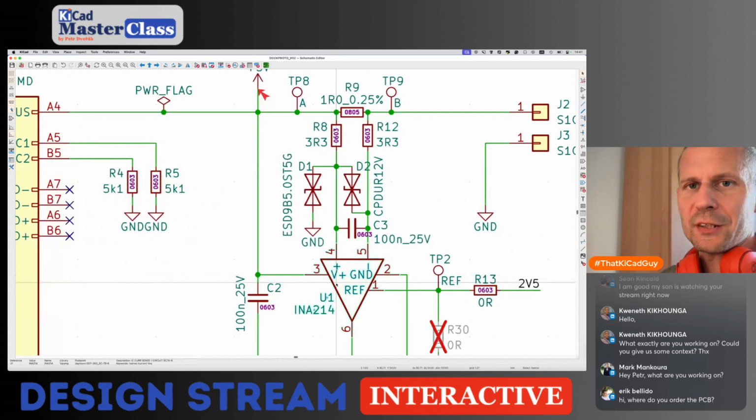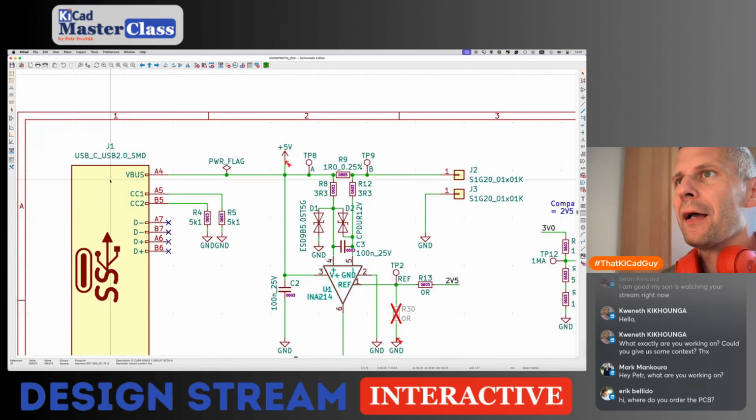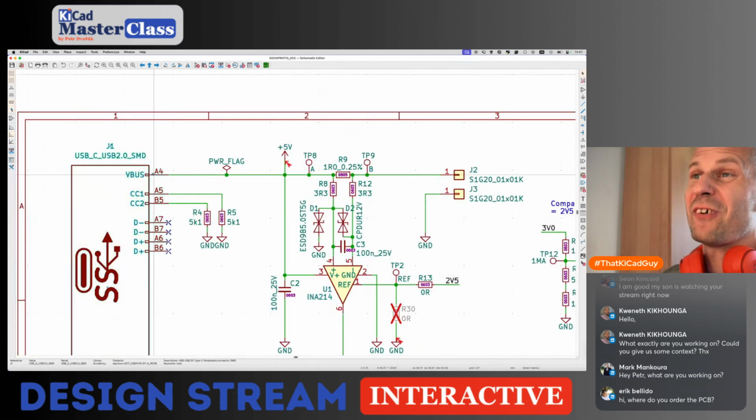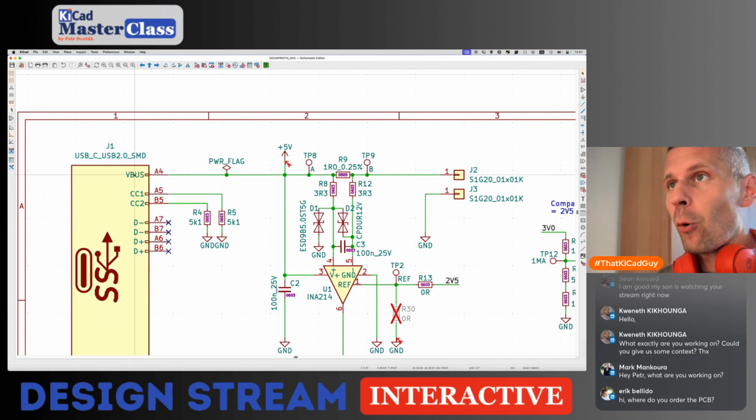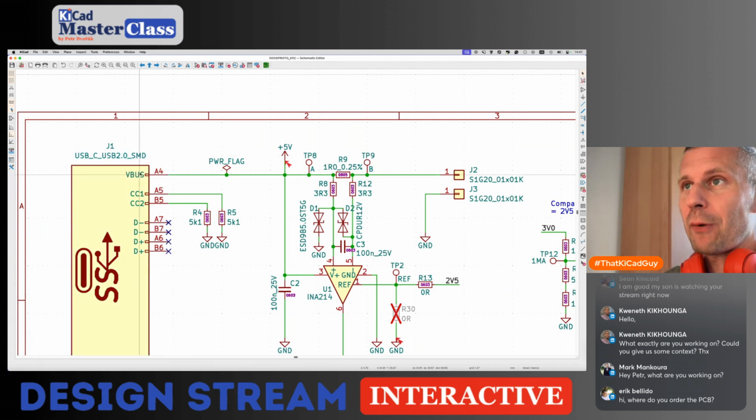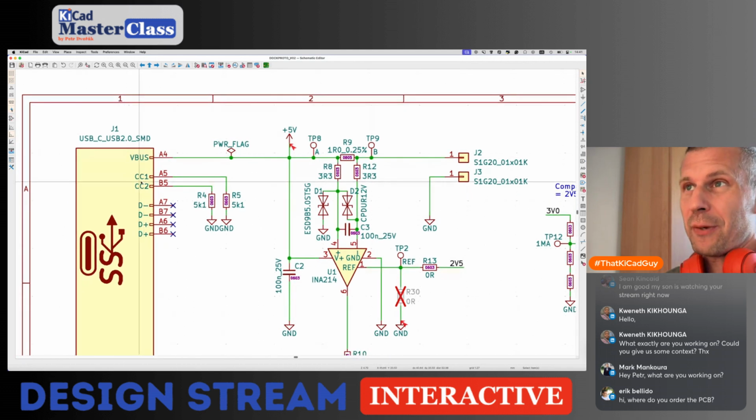There is an input, for instance, of this op-amp, which is marked as power input. And here is a connector which in fact provides the power. Yeah, this is the power driving output, VBus. But the connector pin is set as passive.